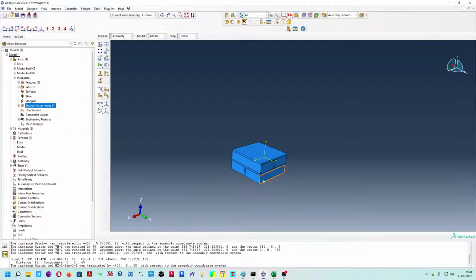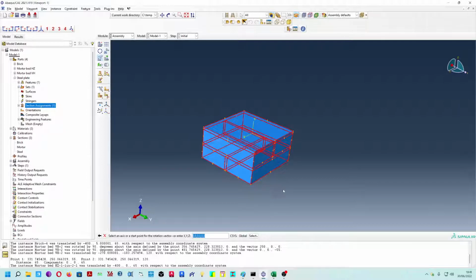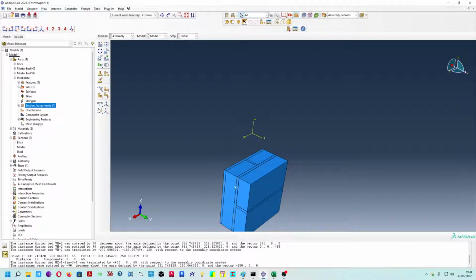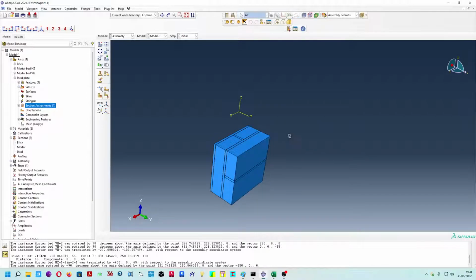Now let's assume I do have to replicate all of this, and I can replicate only on the XY plane. I have to rotate this, done. I have to rotate through an X parallel axis, and the Z is going on the Y, so minus 90. Done. Okay, here we are.